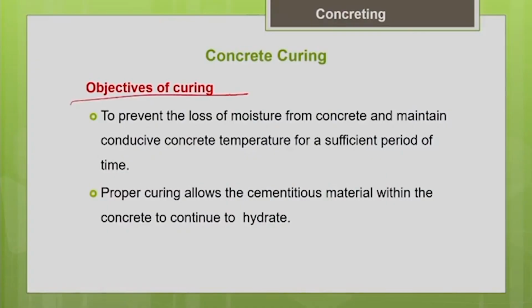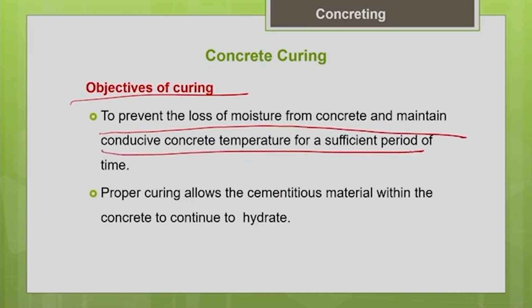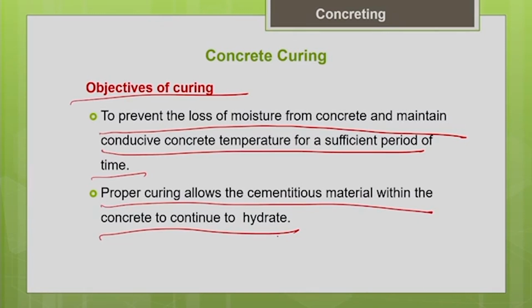So, what are the objectives of curing? To prevent the loss of moisture from the concrete and maintain a conducive concrete temperature for a sufficient period of time, so that the hydration process will continue, so that cracking will not happen. Shrinkage cracks should not happen. Proper curing allows the cementitious material within the concrete to continue to hydrate. Since we are supplying water to the concrete for a sufficient period of time, the hydration process of the cement will continue and you will get your desired strength.